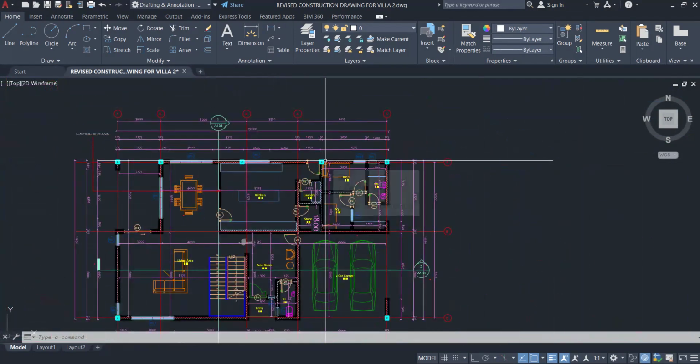I hope you get it. Okay, sorry to interrupt, sir. I think I get where I'm getting it wrong now. So it's not a must for me to follow the architect's grid line? No, no, no. Because I'm having like 7 columns on a row, trying to follow the columns, and I see that I need another column at another point. No, you don't have to. This is just for convenience. The architect just has 5 grid lines in the vertical direction.